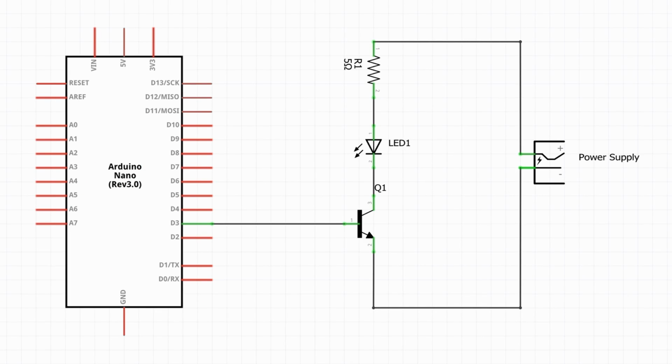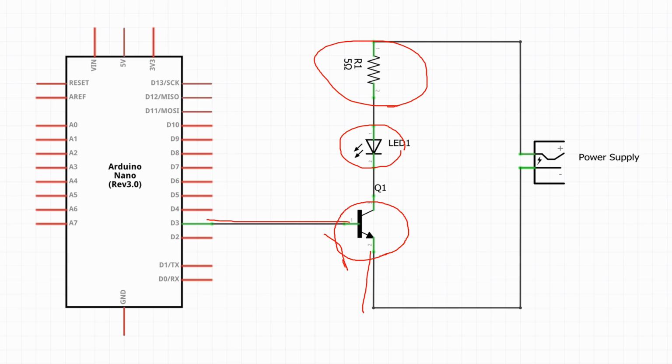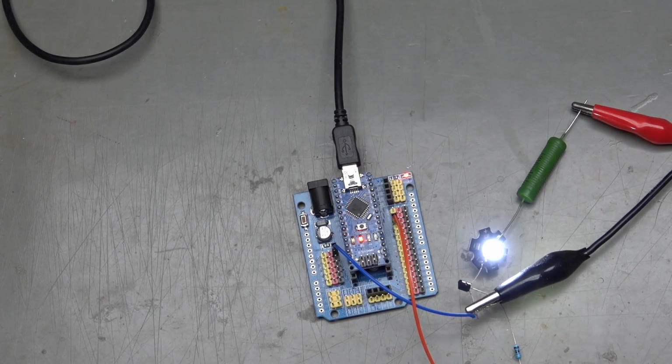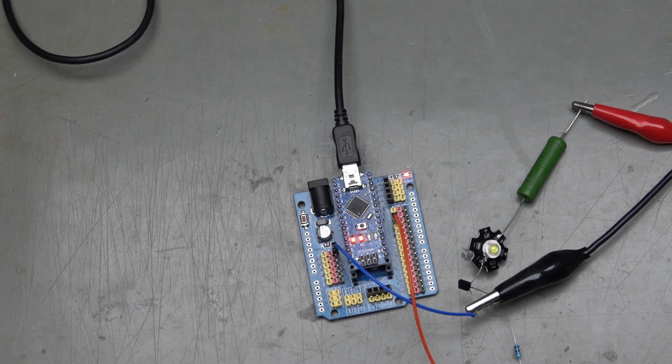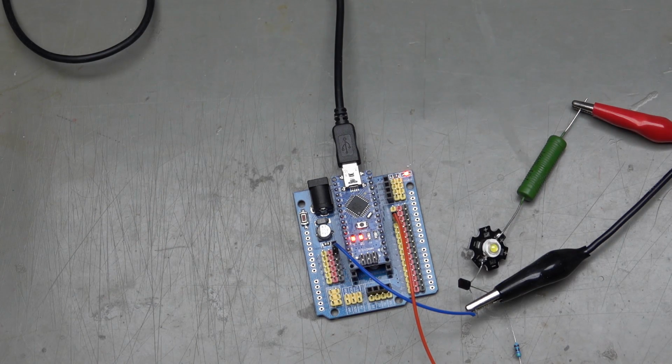We use our 50-50 chance and select an NPN transistor, connect its base to an Arduino pin, connect the emitter to ground and the collector to the usual combination of an LED and a current-limiting resistor. A small base current should now produce a larger current through the LED. We can try it out and build a powerful blink sketch. It works. Cool.